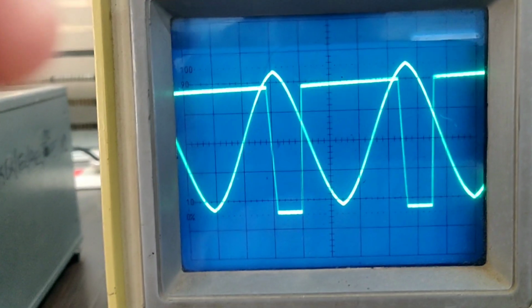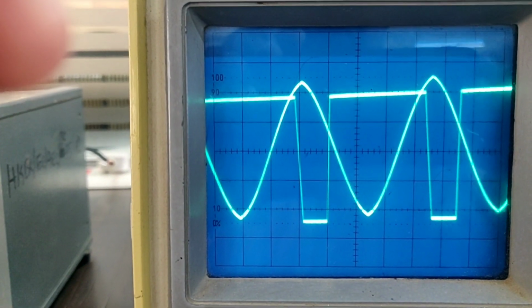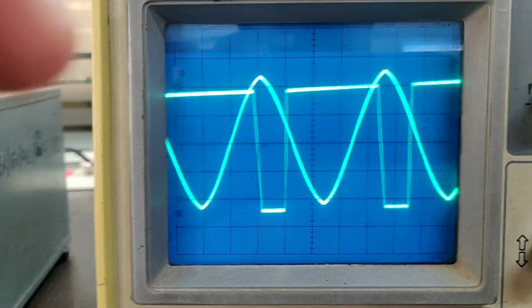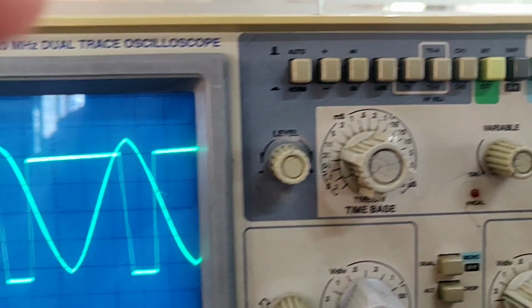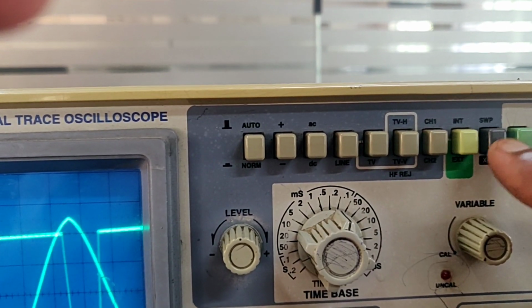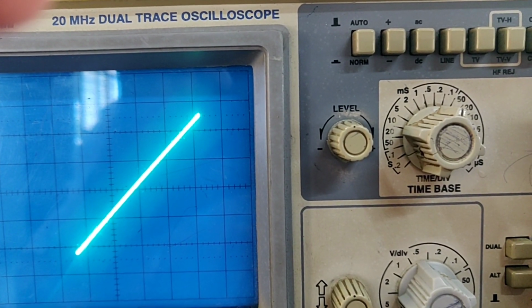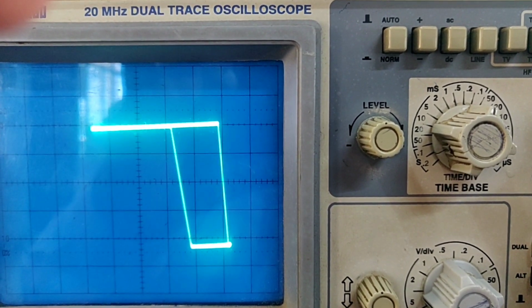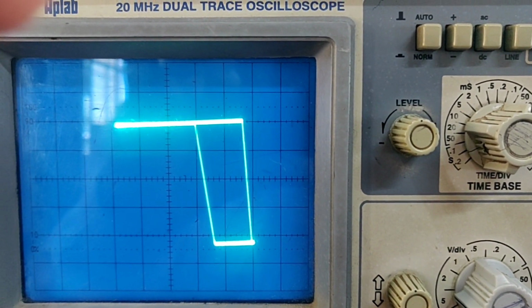Okay, now let us see the measurement of the LTP and UTP using the hysteresis loop. What you have to do for this: display both the waveforms and select the XY key here. Press this. First you may get a horizontal diagonal line, something like this. Release it. Once again press it 1 or 2 times, and you will get the hysteresis loop.